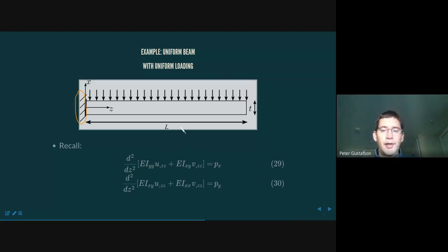I don't give you the cross-section. We're going to assume that what I've given you is the actual IX, IY, and IXY values. And so as givens, you don't have to compute them. That makes life a little bit easier. Unless you're told otherwise, if you have a two-dimensional problem like this, slightly tangentially, this is actually a one-dimensional problem when it comes right down to it, because in the plane of the deflection of this 2D problem, there's really only one deflection to track. So what we're going to find is that that makes it even simpler.